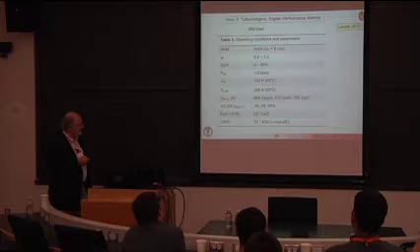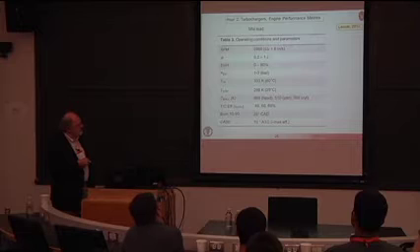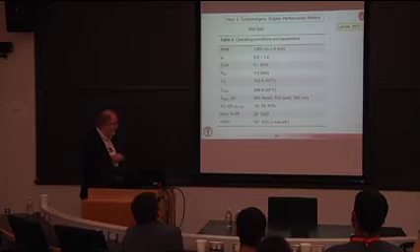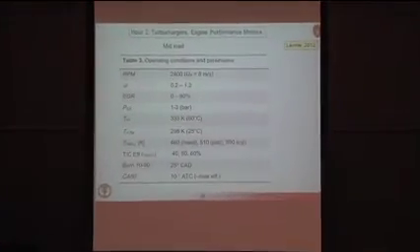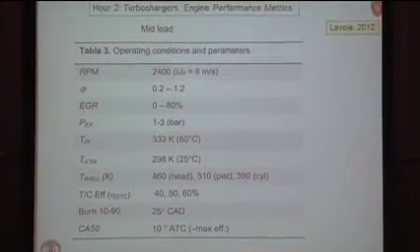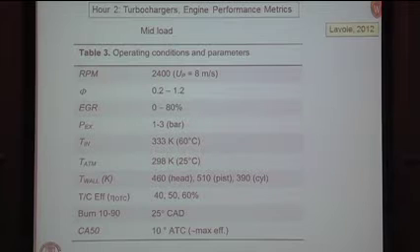And then for the heat transfer calculation, they assumed these temperatures for the components of the engine: the head 460 Kelvin, the piston 510, and 390 for the cylinder. There's some science behind this. These numbers can be obtained from conjugate heat transfer models, which, for example, GT Power offers, or measurements of temperatures in an engine. Here's your turbocharger efficiency. They assumed several, up to 60%. And here are the big assumptions about combustion: that the 10 to 90 burn was 25 crank angle degrees, and the 50% burn occurred at 10 degrees after top dead center.